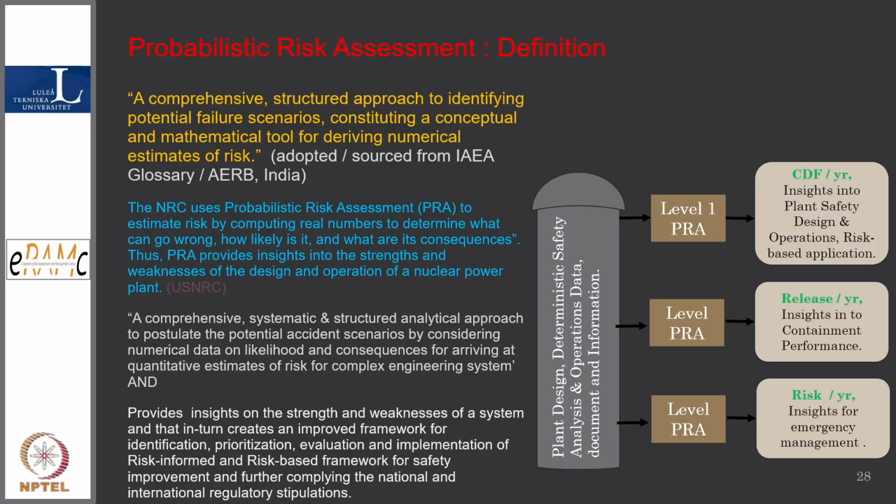That means it does not remain in the qualitative domain. Safety is defined such that the damage probability or frequency is 10 to the minus 6, 10 to the minus 5, 10 to the minus 7. So we can compare and understand the safety, and when we do any modification, we can see how the safety is improved or risk is reduced, because it is an integrated model of the plant.